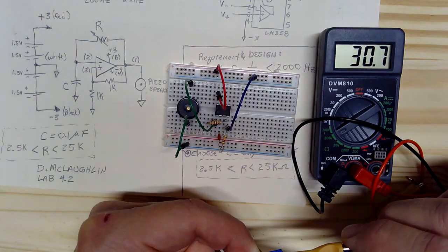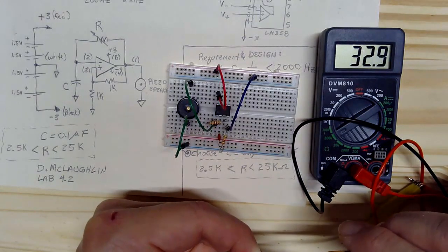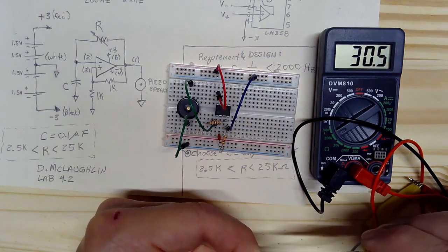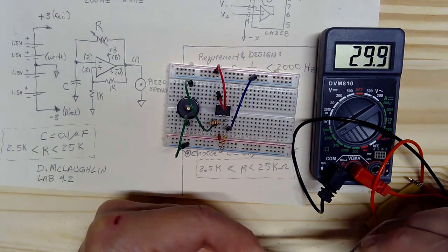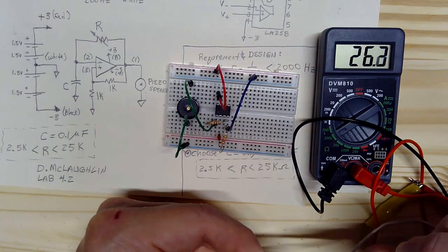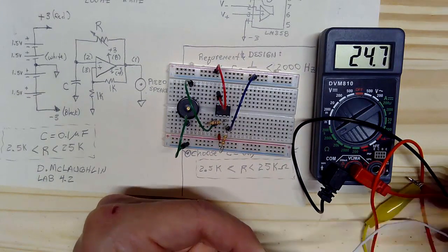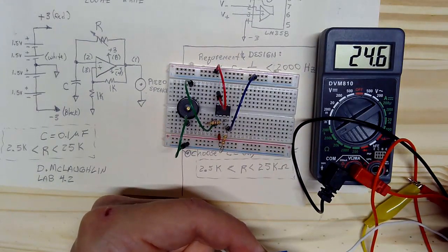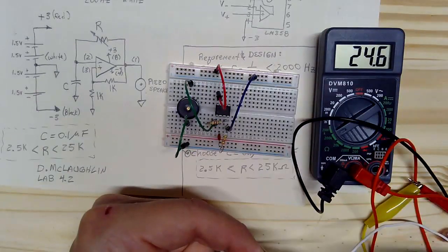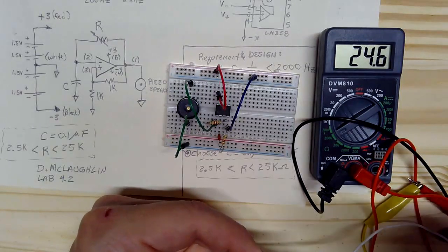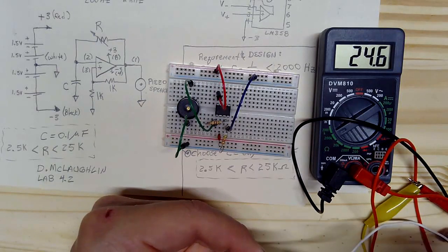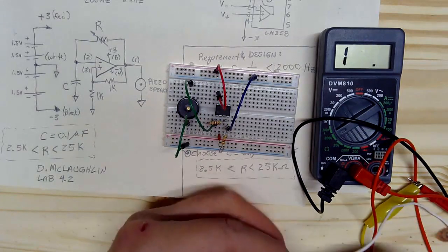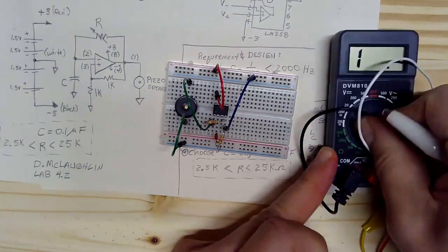It would have started at 100K. So if you take one out of your kit, it's going to be sitting there at 100K, and then you can just adjust it down. We'll bring it down to 25K, and we'll adjust it once we've got it in the circuit. This is the biggest value of the resistor that we'll be using, and since it's the biggest resistor, it's the biggest value tau time constant of the circuit, meaning it's the longest duration pulse or the lowest frequency. So this should correspond to our 200 hertz output, our lowest frequency output.